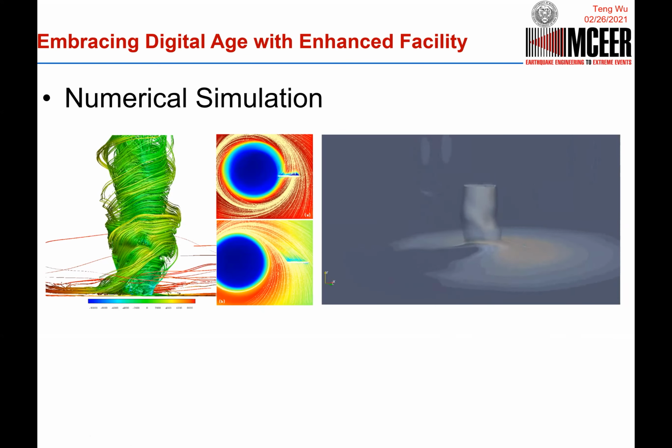But the problem is the computational demand is still too high, even nowadays, with all kinds of high-performance computers. For example, for this tornado simulation, one case has around 600 million meshes to accurately predict the aerodynamic force on the train. More importantly, if you observe this bridge deck or the train structure, they are static, which means the structure has no response.